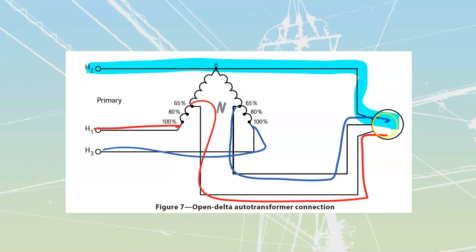We don't have a neutral, but we know that the voltages are balanced around it. Which means that anytime we're using this, we're going to have a slightly different voltage strain on the windings. And for our B, in this case, because that's the one that we're conducting through, we'll always have a little bit more stress. So it's more common with these that you are going to have one winding that can fail separately than the others, just due to the fact that it's always underneath a higher potential value of voltage.